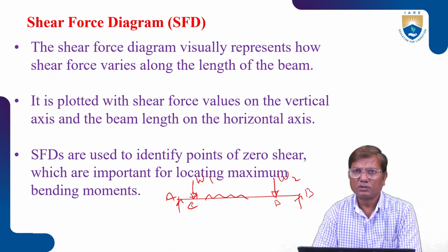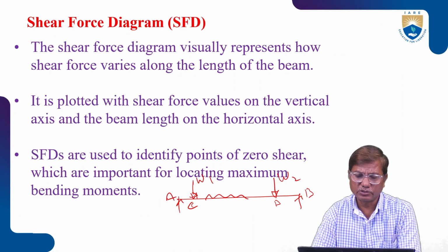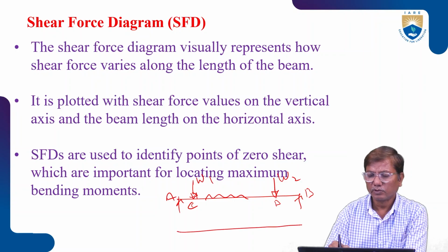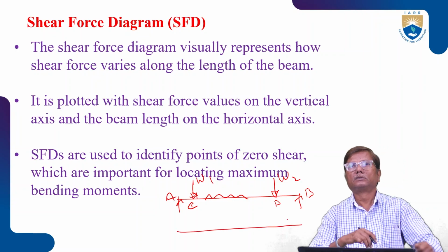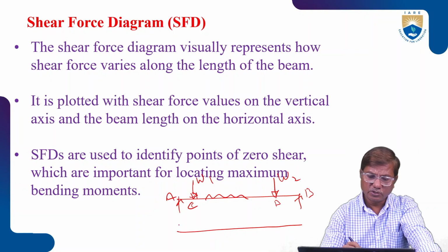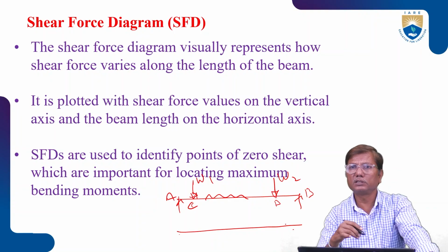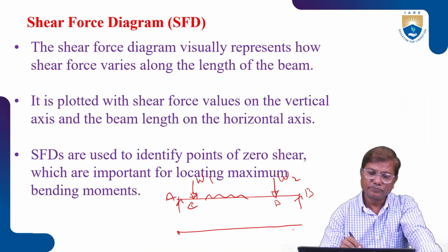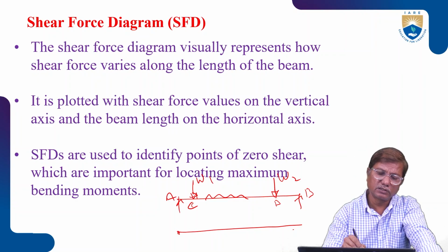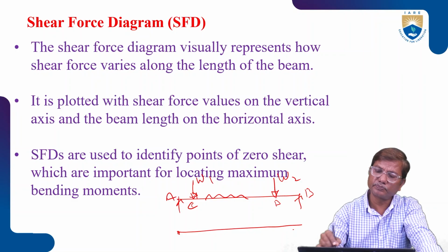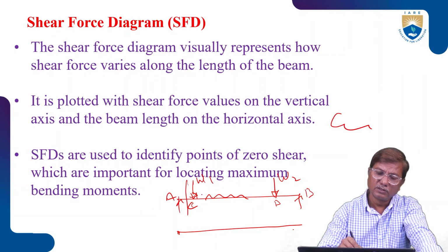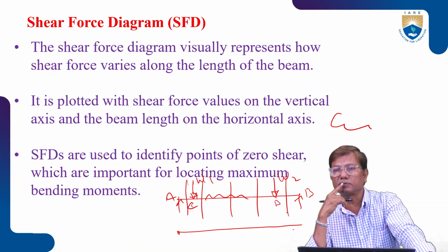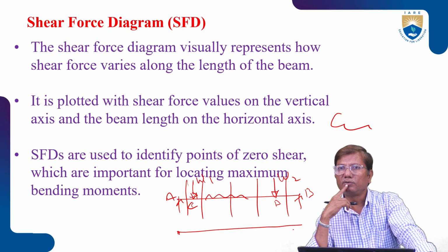How to draw the shear force diagram? What does this diagram show? It shows the values of shear force at different sections along the beam. For that, we have to consider different sections. To calculate the shear force, we need to consider different sections between every change of load.